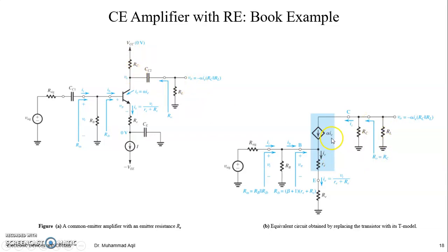Okay, here he writes the AC current IC as alpha IE. It means you have to find IE here, then you can multiply with alpha, you get IC. We already know that these are the same thing. If you find VBE here, or V pi here, then gm times it will be the current here. So these are all equivalent things, right?